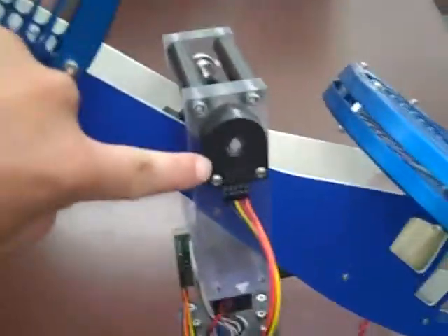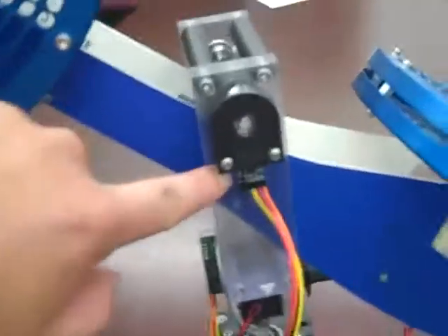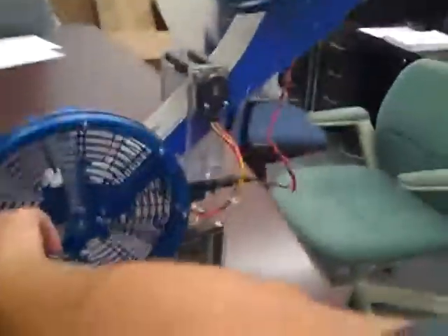Here is what the issue was. This encoder right here, this connection was correct, but as we went down, it gets connected again right here. This connector had been flipped. So its signal was bad, causing it to just want to shoot up to this elevation point. Well, as soon as we flipped it and pressed it again, it worked great.